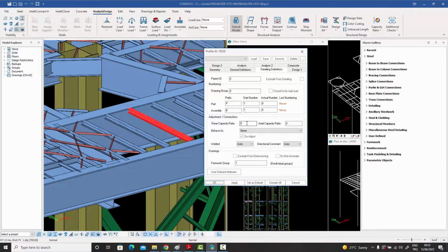If I were to write 0.3 over here, what that would mean is that when I went through all the load combinations and looked at the V22 and V33 variables, and converted them into the equivalent shear capacity of this member, then the combined value, which in the case of V22 and V33 would be the square root of the sum of the squares, is about 0.3 or 30% of the shear capacity. Usually V33 will be very small, and V22 will be dominant, maybe 90% or 95% of the load.